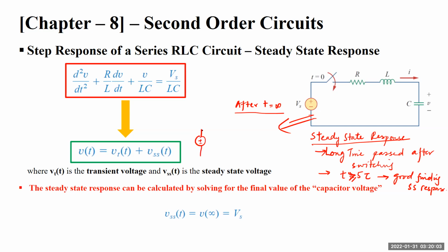So we have a voltage source and a resistor. The inductor will be acting as a short circuit because it will be completely magnetized to the value of current flowing in the circuit, and the capacitor will be behaving as a completely charged capacitor, which basically results in the capacitor behaving as an open circuit.